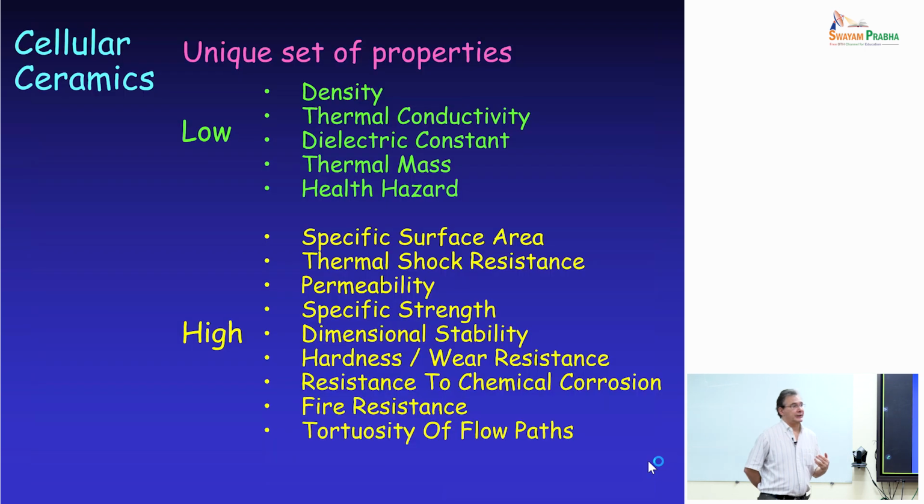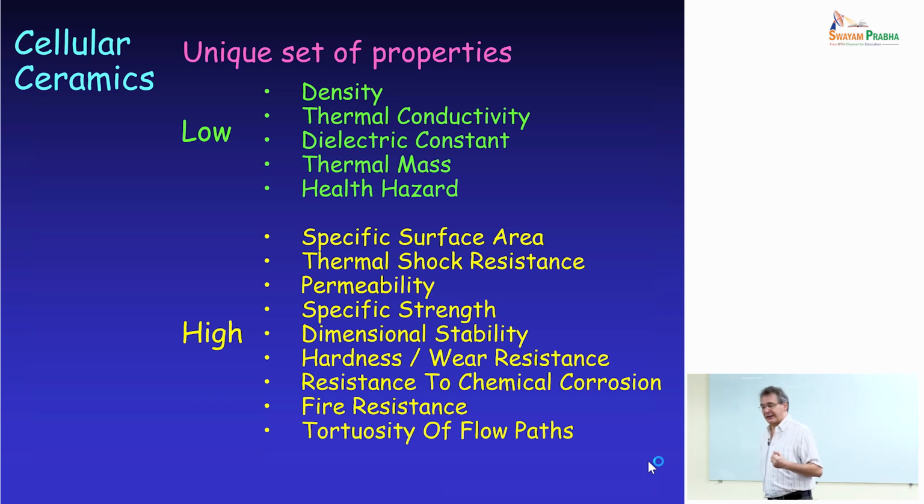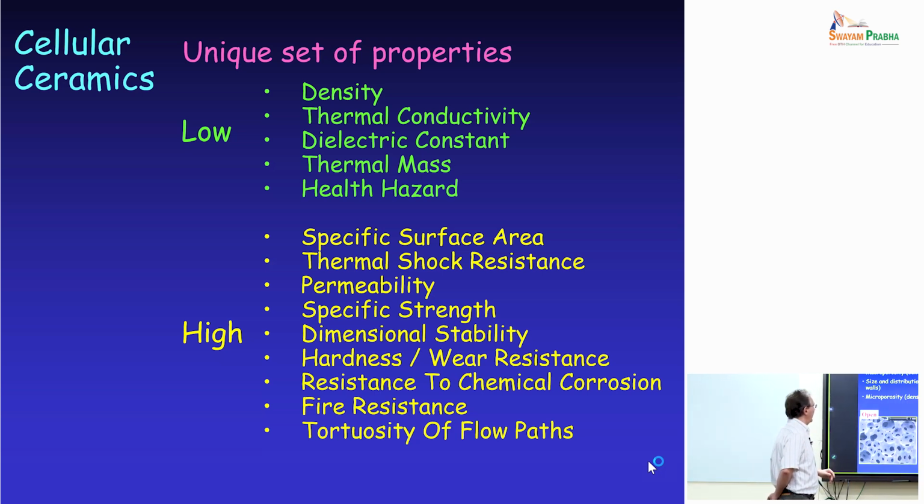And besides extending the properties of a solid, ceramic foams have a unique combination of properties, because at the same time, they have low density, low thermal conductivity, low dielectric constant, low thermal mass, and with respect to using fibers, for instance, a ceramic foam does not create a health hazard. At the same time, they have a high specific or geometric surface area, thermoshock resistant, and I don't need to read all of this, but you can see that you have a unique combination.